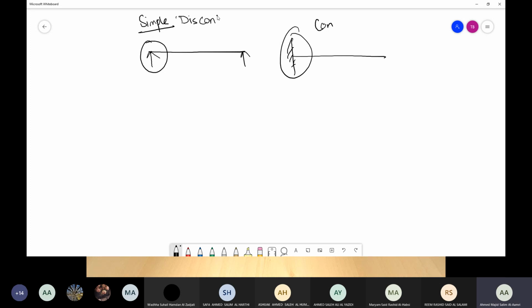Okay. Now what happens if I try to draw a simply supported case? In simple discontinuous support, the bending moment is going to be equal to 0. So 0 is 0, and then due to the fact that we are having a UDL, you will see that it will bend as a parabolic profile.